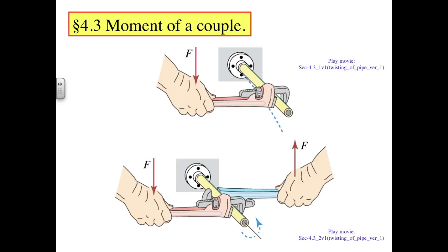The squeezing results in a normal force on either side of the cap. These are equal and opposite forces, but are not a couple because their lines of action are coincident. A significant squeezing force is necessary because the largest friction force you can exert is proportional to the normal force.